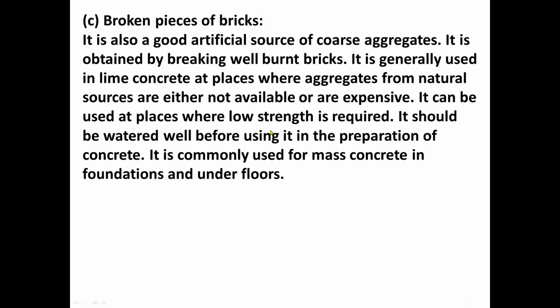Broken pieces of bricks. It is also a good artificial source of coarse aggregates. It is obtained by breaking well-burnt bricks. It is generally used in lime concrete at places where aggregates from natural sources are either not available or are expensive. It can be used at places where low strength is required. It should be watered well before using it in the preparation of concrete. It is commonly used for mass concrete in foundations and underfloors.